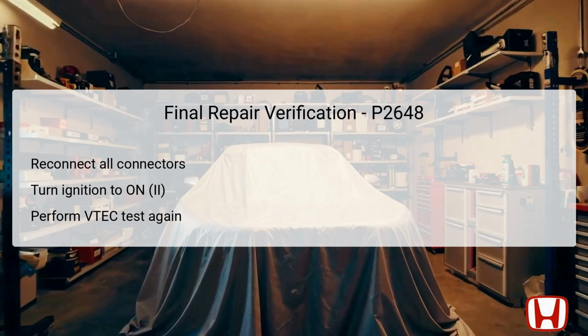The technician will again utilize the HDS to perform the VTEC test. Similar to the initial assessment, this step will confirm whether the issue has been resolved or if the DTC reappears. Furthermore, checking for any pending or confirmed DTCs is essential. If DTC P2648 is not indicated, troubleshooting is considered complete, indicating successful repair.